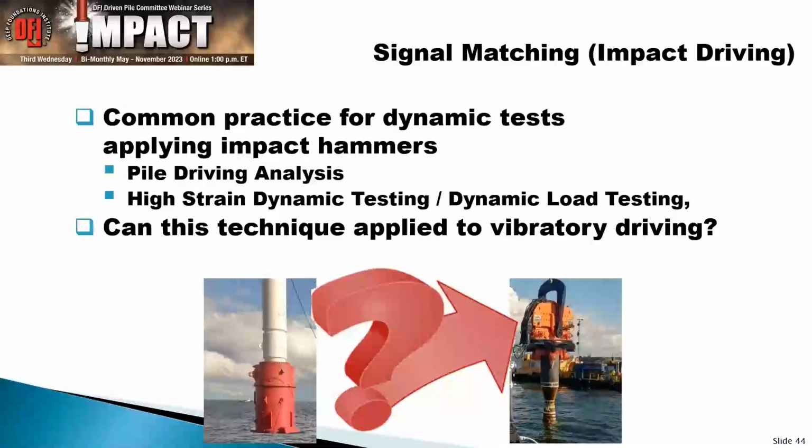As I said, very common for dynamic testing. Since the early 1970s, this is being done time and time again. We do PDA during the pile driving, to get a rough indication of what the capacity is with simplified equations, and then you do your high strain dynamic testing, or what is commonly known as dynamic load testing, to analyze your data. And then the question is, well, if this is commonly done for impact driving, why can we not do this for vibratory driving? Or maybe more basically, can we apply this technique to vibratory driving?